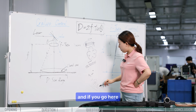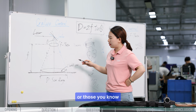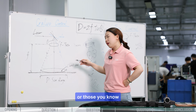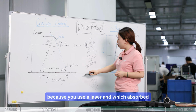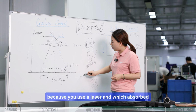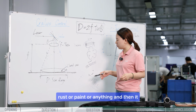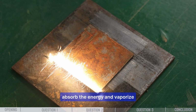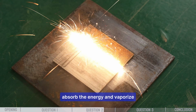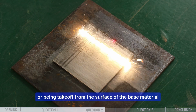And if you go here, you get very gentle cleaning. For laser cleaning theory, we come back to that: you use a laser, which is absorbed by the surface, rust or paint or anything, and then it absorbs the energy and vaporizes or is taken off from the surface of the base material.